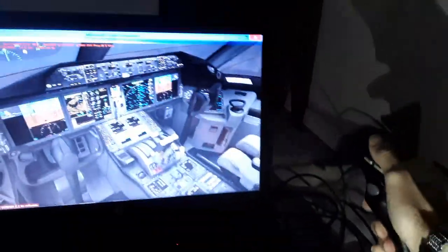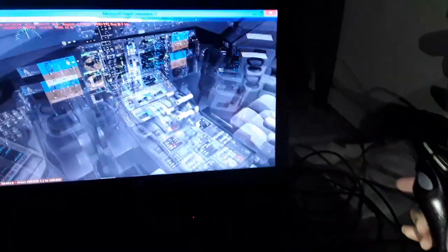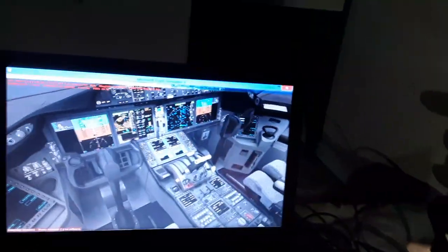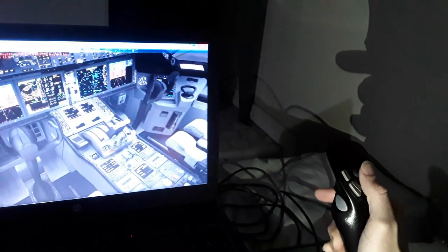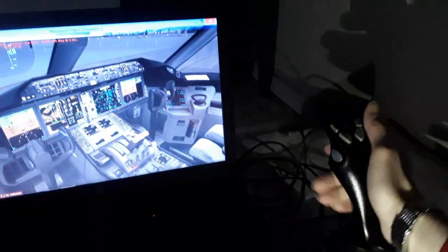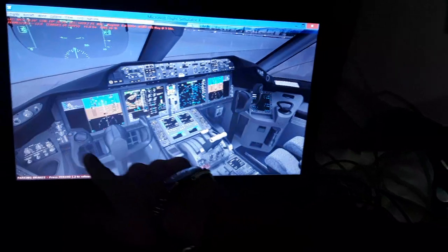As you can see, we have the size here, so you can climb and you can descend. You can make turns to the left and to the right as fine. So this is the vertical column of the yoke of the Boeing 787. You make the elevator, the horizontal tail section, the elevator climb and descent, pitch up and pitch down the nose of the aircraft. You can hold neutral, you can make turns left and right using the control wheel. This section is the control wheel.